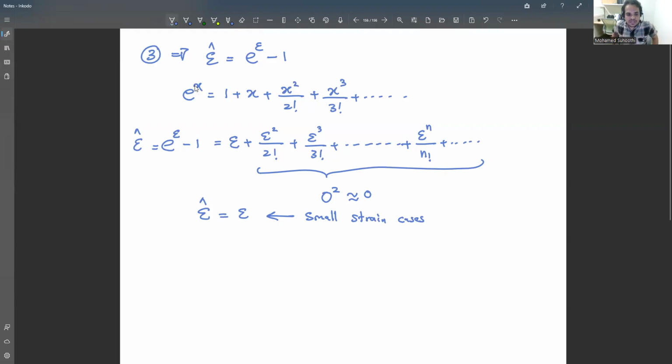So this is the thing you studied in your strength of materials class. In strength of materials, you never differentiated these two, right? True strain and nominal strain. Because you studied under this assumption, the small strain assumption. So there, the difference between true strain and nominal strain you can ignore. Again, this is for the one dimension case I am telling, right? We will derive this for the two dimension case, that means the general case, in the next video. But for the moment, you understand the meaning of this small strain assumption, right?